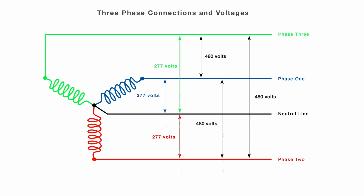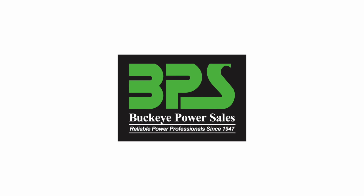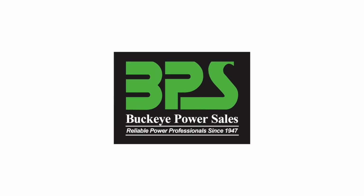The series star three-phase connection represented here is a 277 phase to neutral and 480 phase to phase arrangement, with the ratio being phase to neutral voltage multiplied by root 3. Series star three-phase voltages can also be 220 volts phase to neutral and 380 volts phase to phase. In a parallel star connection, there is also the option for 127 volts phase to neutral and 220 volts phase to phase. If you have questions about three-phase generator systems and configurations, contact your authorized Kohler distributor for assistance.